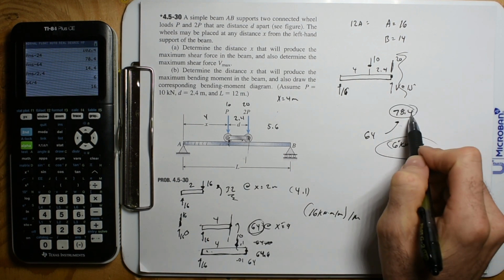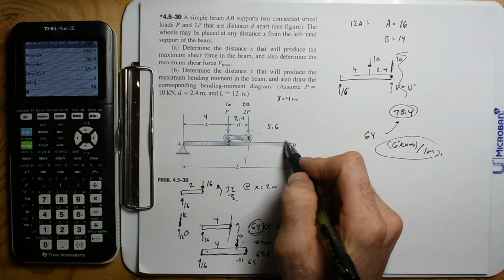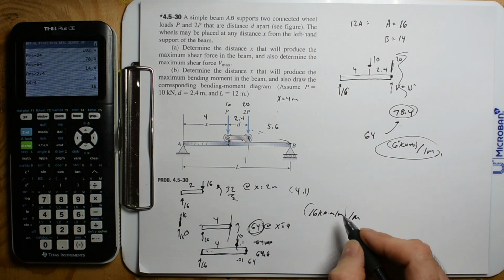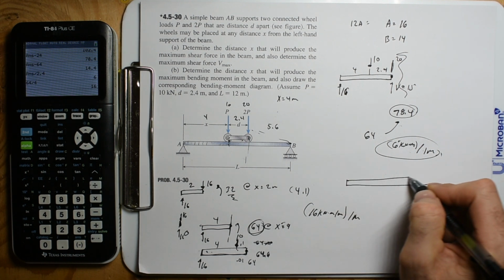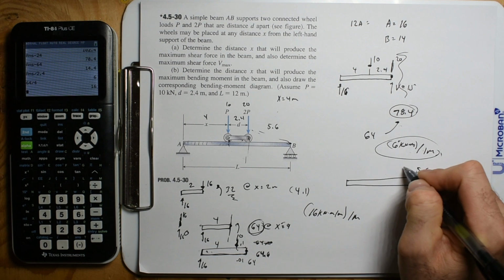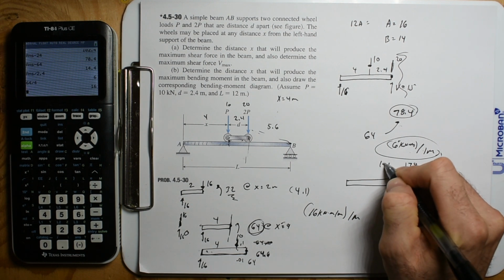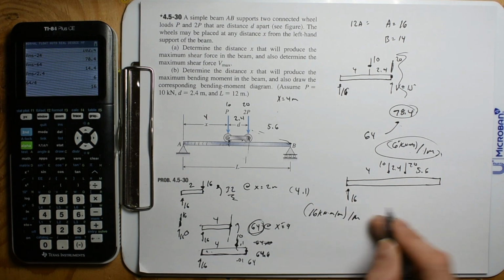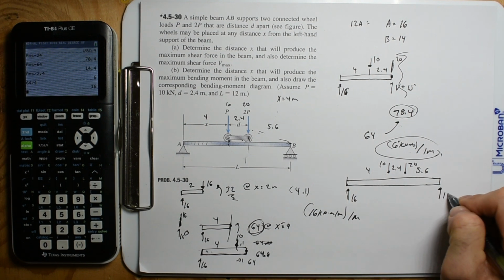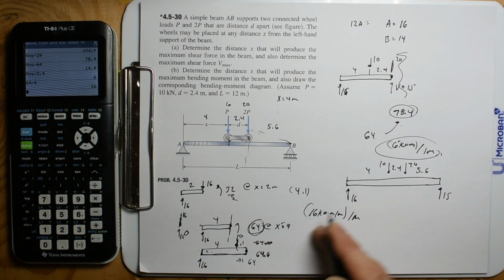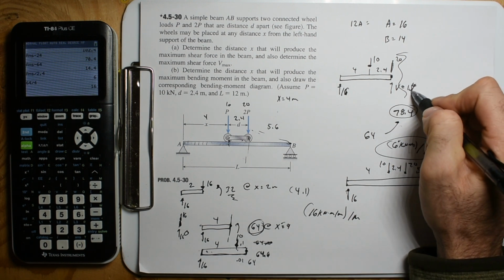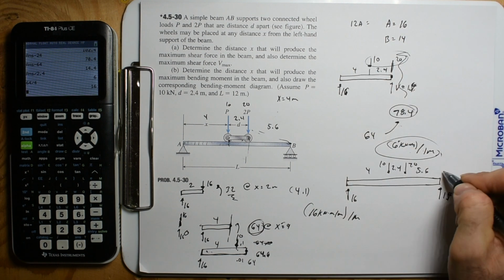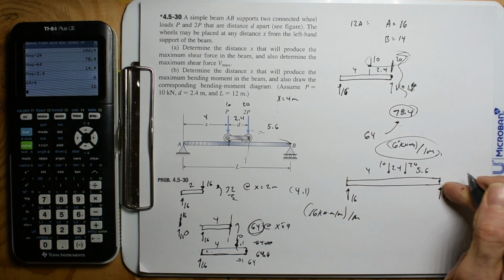And then once we get to 78.4, we're probably going to go back to 0, because let's take the bending moment all the way to the other end. So we have 5.6, 20, 10, 2.4, and 4. And we have 16 up. It doesn't matter what we have here, but obviously we're going to have 15 up. No, I'm sorry, shoot, this should be 14. 16 plus 14 is 30, which balances those forces. But like I said, it doesn't matter what's happening here because we're going to sum the moments from here.